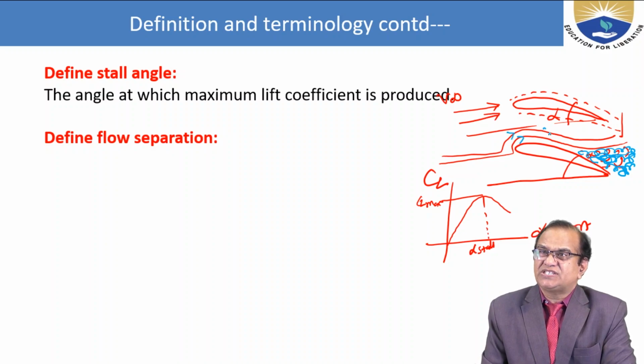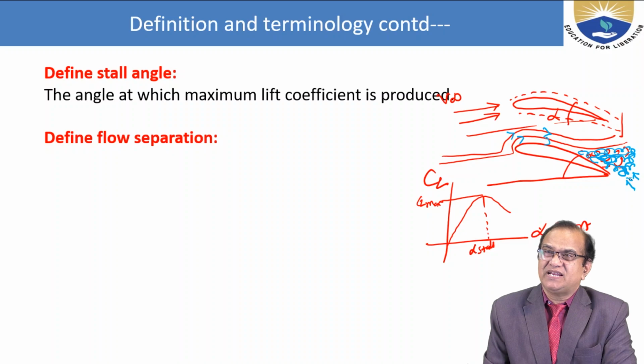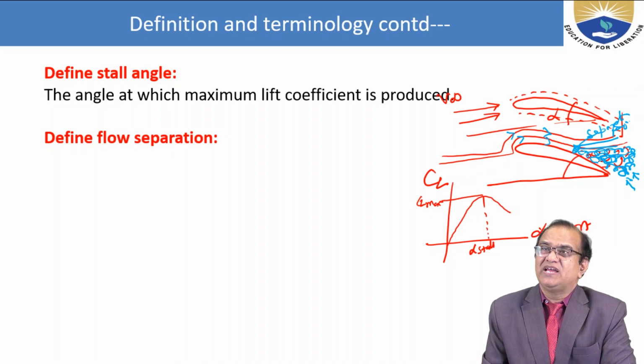This kinetic energy, as it is going due to the boundary layers, the energy of this is reduced, and here the pressure, which is called the adverse pressure, is pushing, and this is the separation point. So at this point your flow will not be attached and it will move upward, and this area will be useless. The wing in this area is not producing lift, however it has started producing more drag.